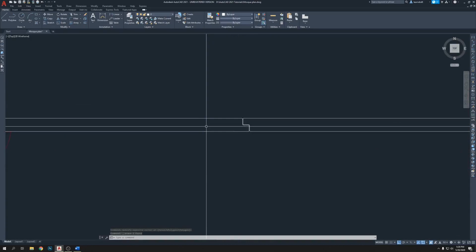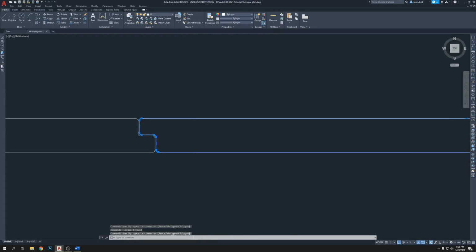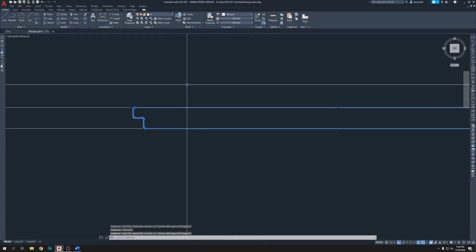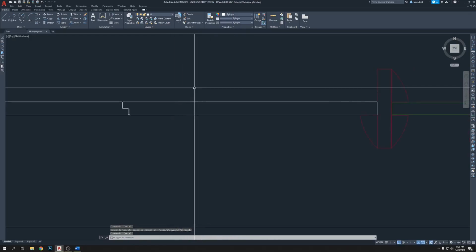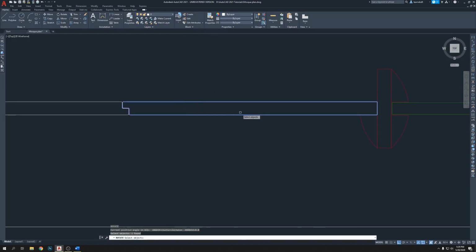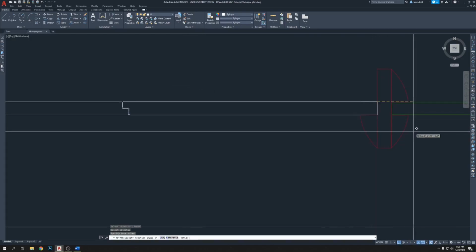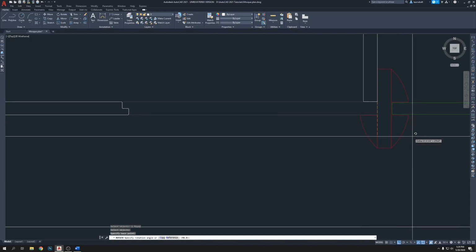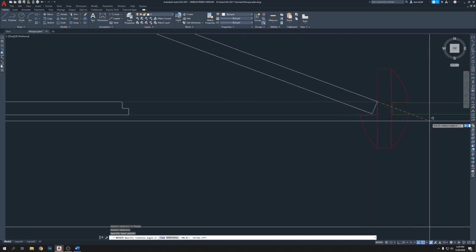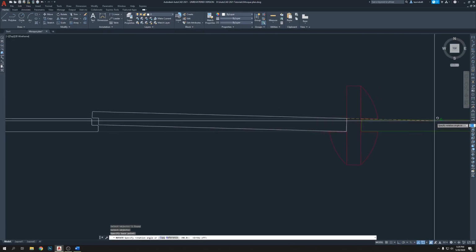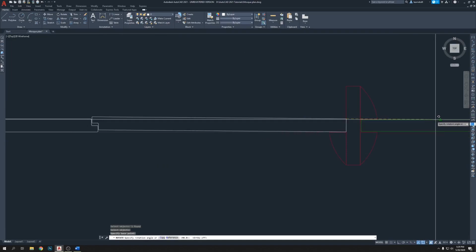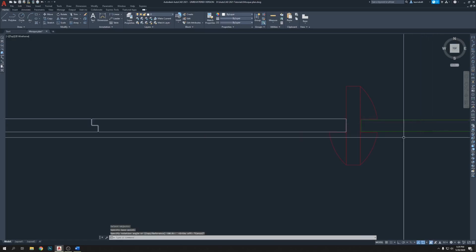So let's say this one is going to stay, and this will open and close. Let's see if this one can open and close easily without touching the frame. RO, enter, select this one, pivot from here, press F8. So this is coming this way, this way, and without touching it, it's going through without touching, but this face needs to be a little shorter.